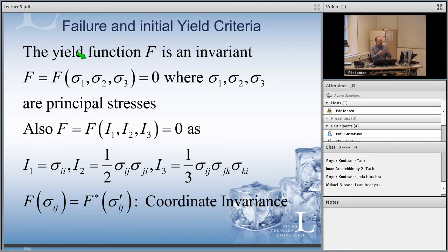That's what you have. It's like when you're solving this eigenvalue problem. This is what you find. You can find your principal stresses, and then you only need one index. So the largest one you say sigma 1, the middle one sigma 2, and the smallest one sigma 3. And when you have the full tensor properties, you have double indices.